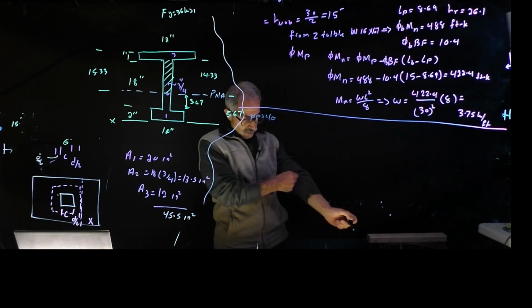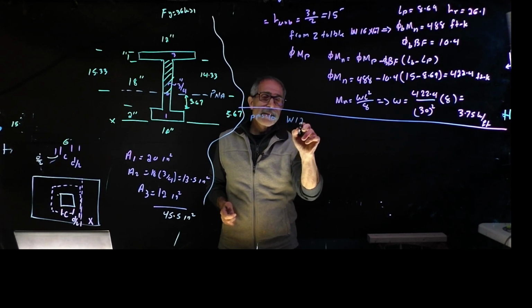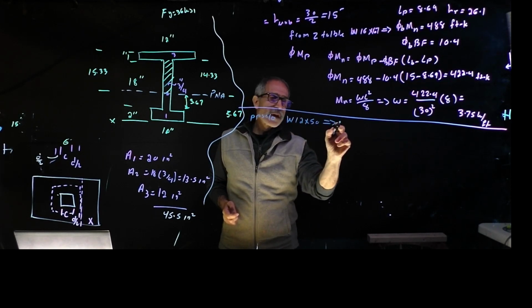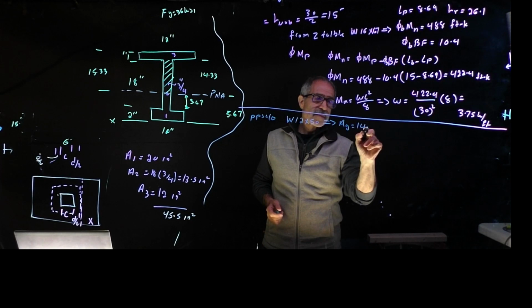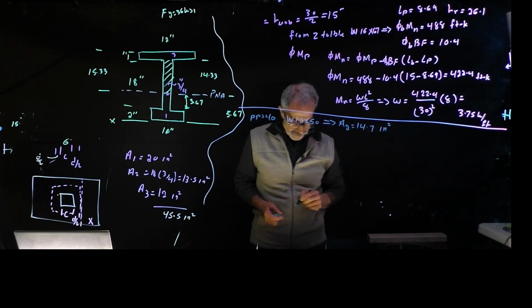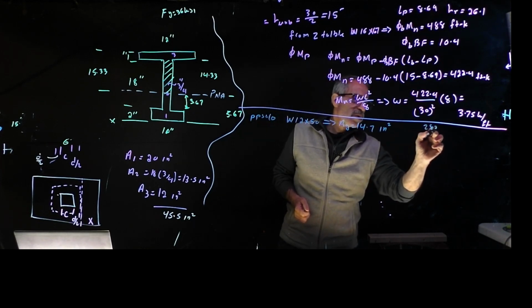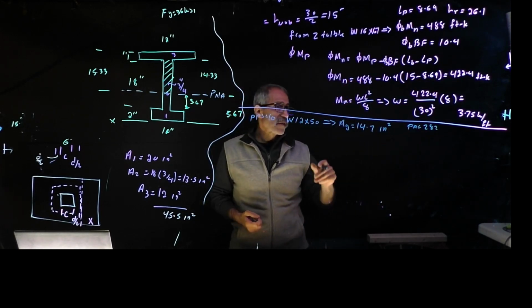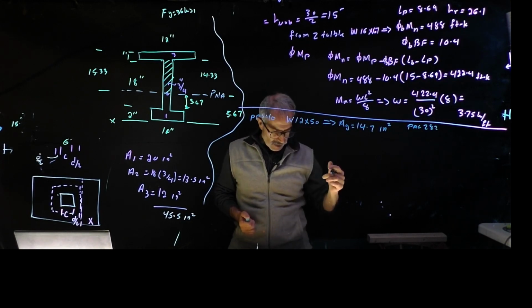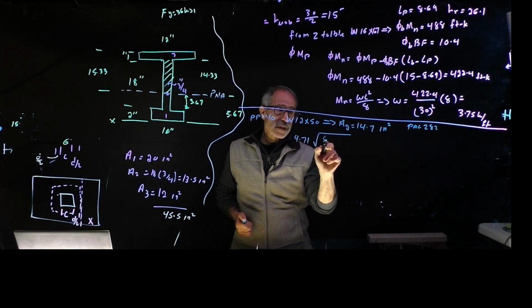We're going to go into your handbook, and for W12x50 we have the gross cross-sectional area come out to be 14.7 square inches. I think this is handbook page 282. And from there you want to know, for the critical buckling, what is your ratio going to stand for? So what is 4.71 times the square root of E divided by Fy,